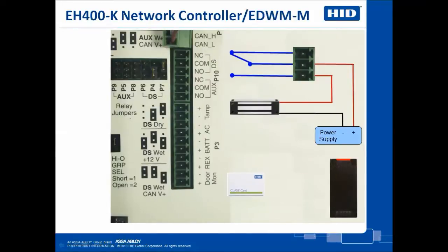Magnetic locks are inherently fail-safe devices. Removal of power results in an unlocked door. Devices of this type should be connected through the normally closed contacts that are provided. This enables presentation of the card to de-energize the device for the configured unlock time period so that the presenter may go through the door.